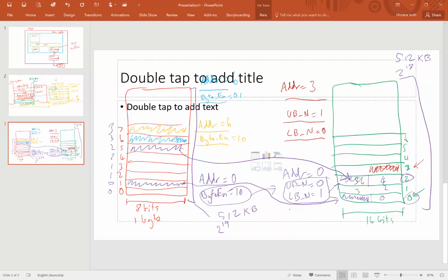But it's fair enough if you just want to do a very similar test as you did for the first one, making sure you test a number of different addresses and different transactions. With this interface, you can also do word transactions, so you should be testing store word and load word as well, which will operate by transferring 2 consecutive 16 bits.